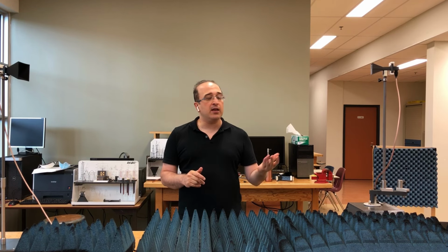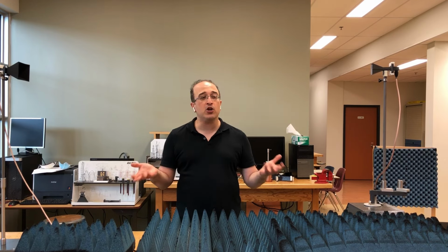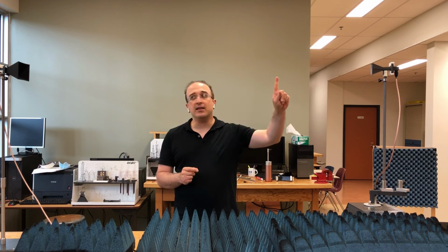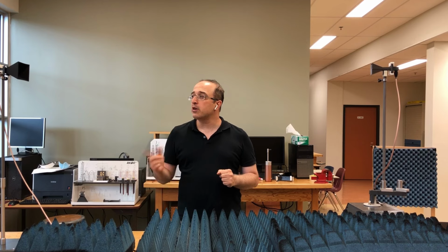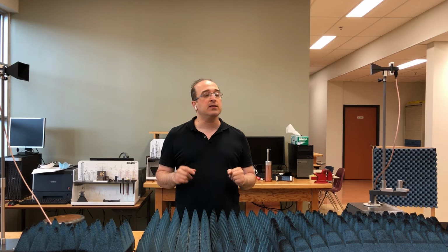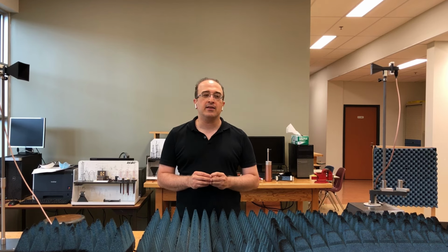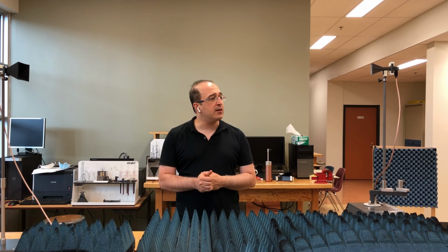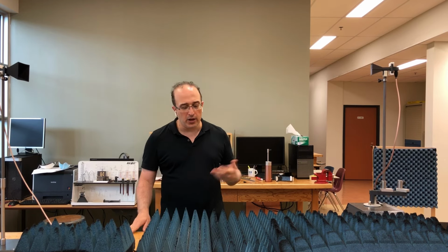For this gain measurement, or to be more accurate, for this gain comparison measurement, I have mounted the smaller horn in its H plane. Currently it is vertically polarized, and I've also rotated the larger horn antenna compared to the previous measurement so that it is also vertically polarized. So now both of them are vertically polarized. I'm going to measure the H plane, and then use that to calculate the gain of the other two antennas. I don't really need to do an E plane of this antenna, so I'm just going to measure the H plane of this smaller horn, and I use that.